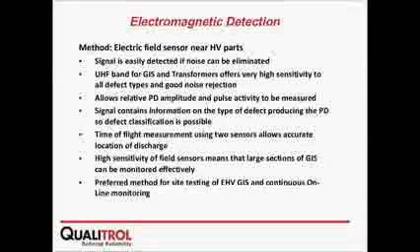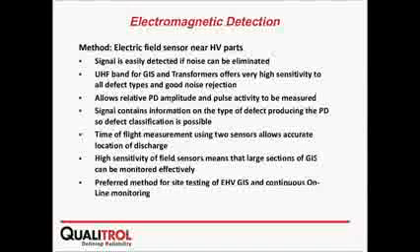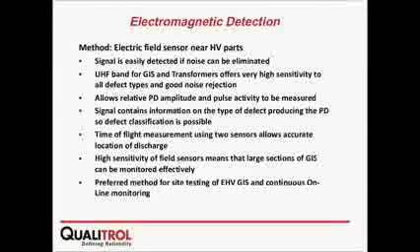So it is the preferred method for high voltage test and online continuous monitoring. For a high voltage test, if you have to do maintenance in a station and have to apply a high voltage test later on, and you want to compare the classification, you want to synchronize with the frequency. So for instance, some customers use 60 hertz, others 50.